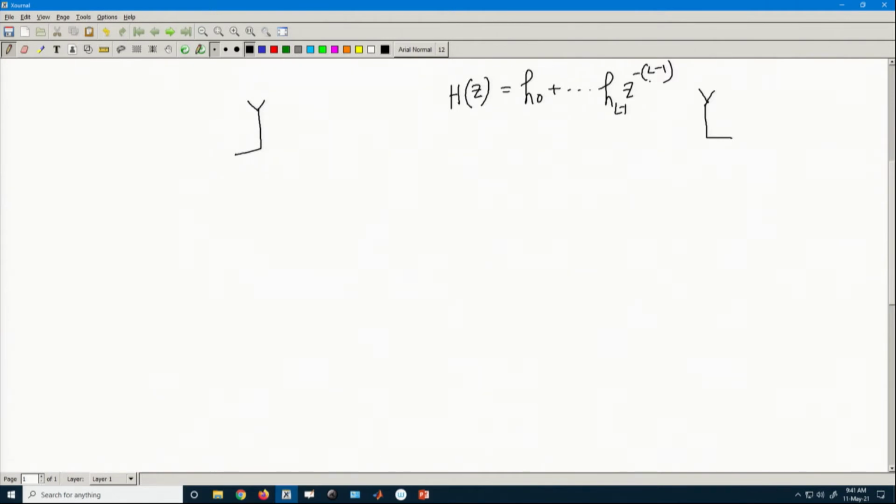That was the filter, and finally we have seen how exactly OFDM works with CP addition, CP deletion at the receiver, and how the whole channel becomes circular, what the advantages are, and what the effect of CFO is. We have also discussed what the spectrum is when you do FFT, IFFT, and what the time domain spectrum of it is. Everything we have discussed.